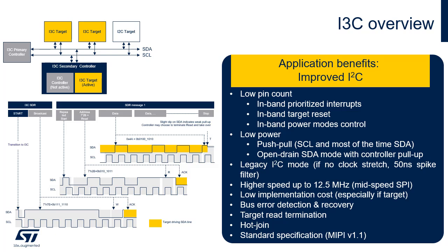The master then turns on a pull-up resistor and goes to open drain, allowing the slave to acknowledge by pulling the SDA line low. At this point, the master continues to toggle the SCL line and release the SDA line, allowing the slave to drive SDA to send 1 byte of data for A followed by T. T equals 1 informs the master that there's additional data, whereas T equals 0 signals the end. Here there's additional data, so the slave drives SDA high until SCL goes high, at which time it releases SDA.